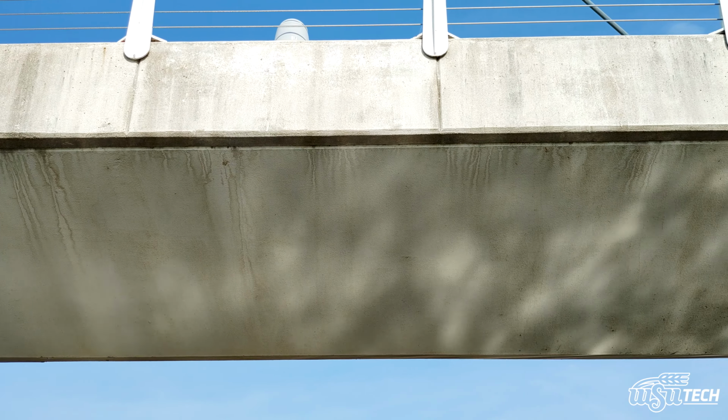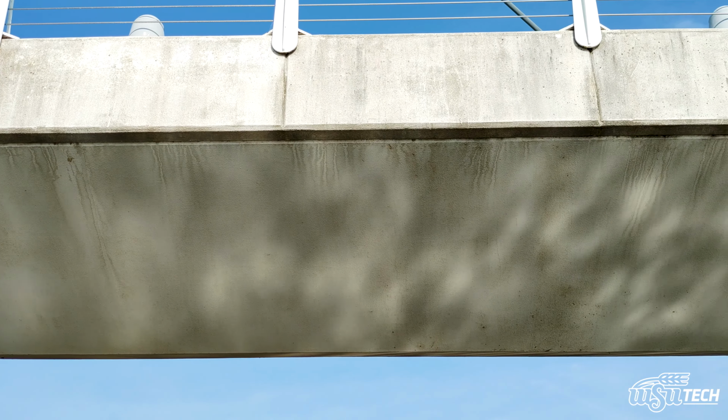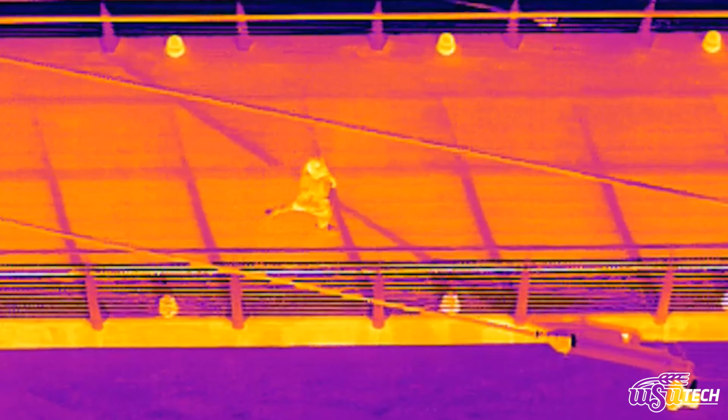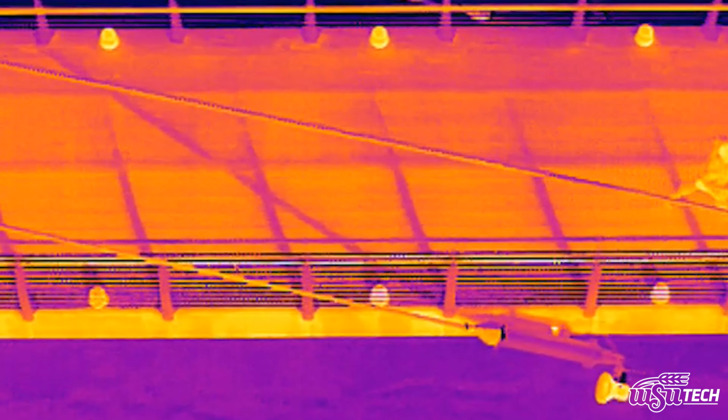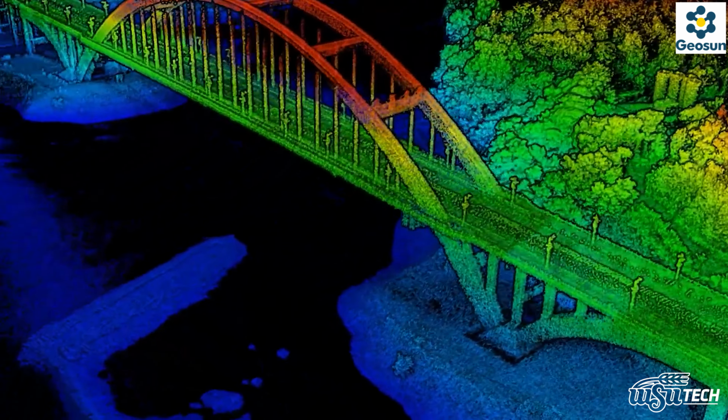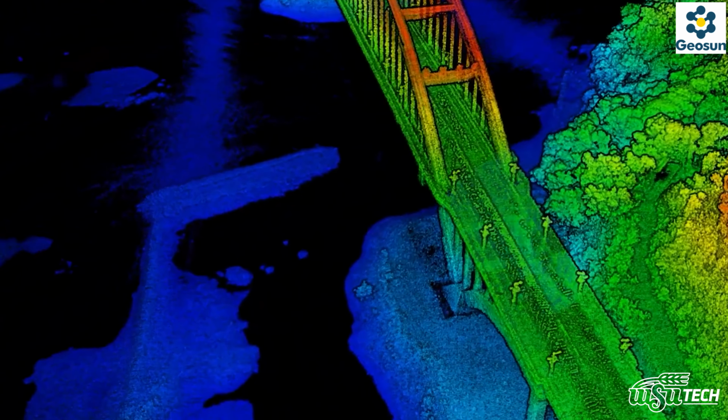By now, you should have a clear understanding of how photogrammetry, thermal imaging, and LiDAR each play a role in modern bridge and roadway inspections. Photogrammetry gives you sharp, measurable visuals for modeling and documentation. Thermal imaging reveals what the eye cannot see, helping you detect moisture, heat loss, and hidden damage. LiDAR captures precise, 3-dimensional data that is ideal for elevation changes, erosion, and complex surfaces. Each tool has its strengths, and each one requires proper setup, planning, and execution. But when used correctly, they give you the information needed to support real decisions.